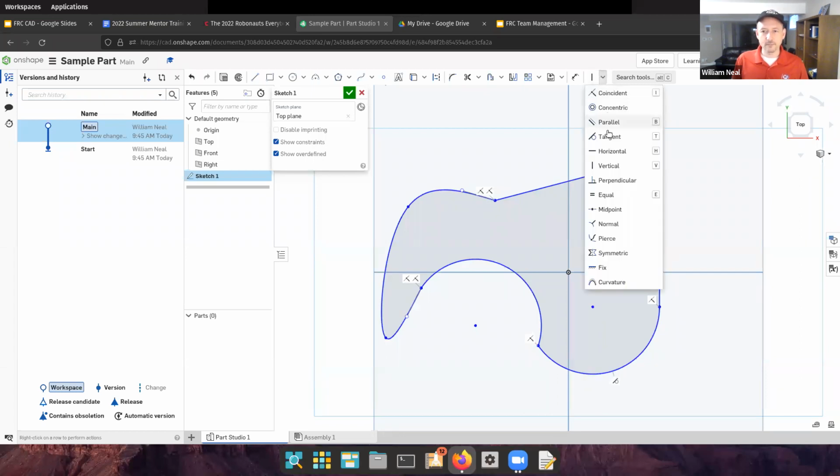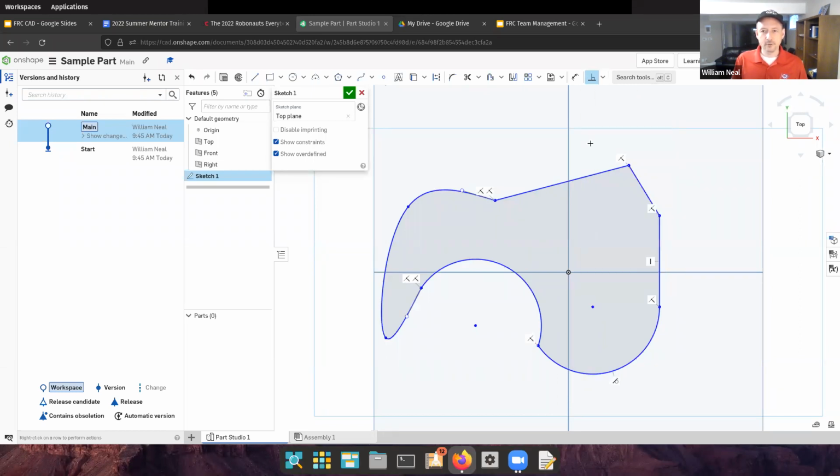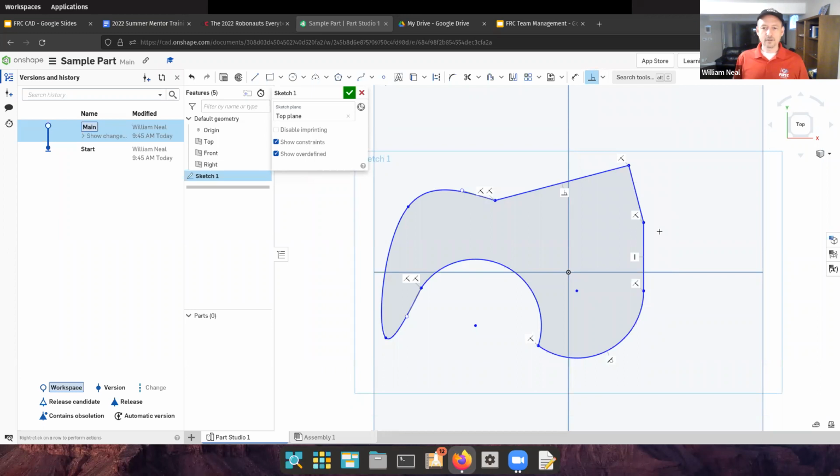Let's make these two ones perpendicular. Okay, so go to my perpendicular. Now I'm in the perpendicular tool. You see it's showed here. The next two lines I click should end up being perpendicular. Good. And since the rest of my drawing is not constrained, it shifts the shape of everything else to maintain the closed loop and the constraints that I already have.